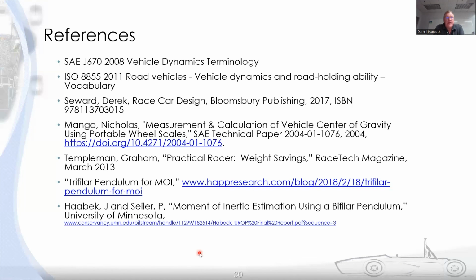So that's the kind of thing I look for as a design judge: do you really understand all of these things, and have you considered the trade-offs and made a good compromise between weight, center of gravity location, and performance of your vehicle, right? The lower center of gravity is a very basic first principle of your vehicle.